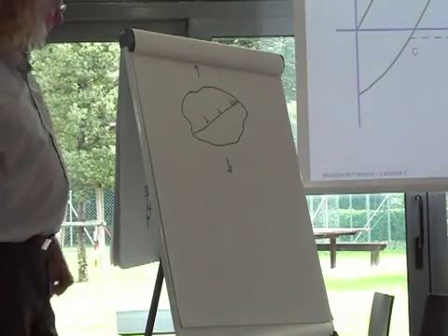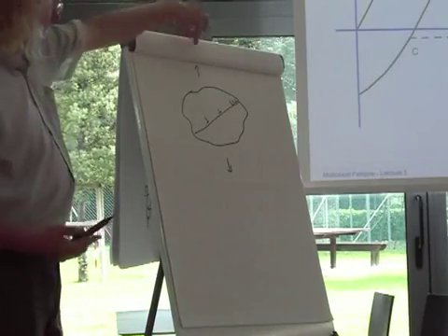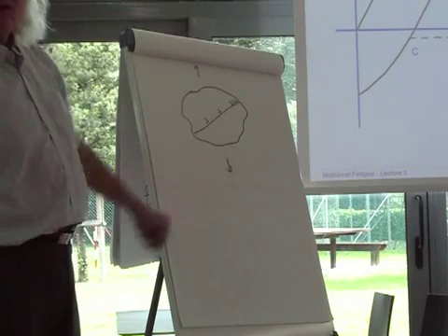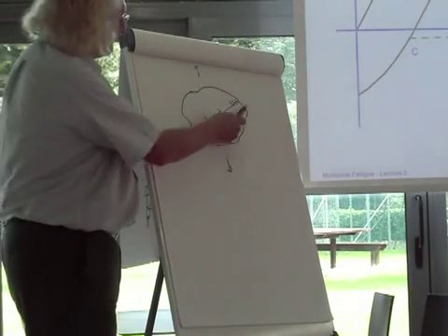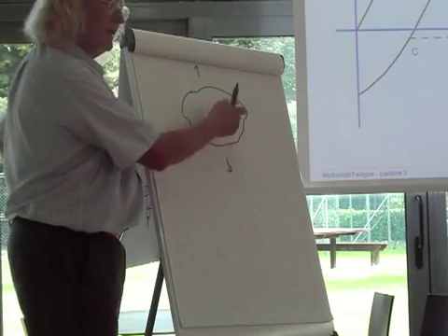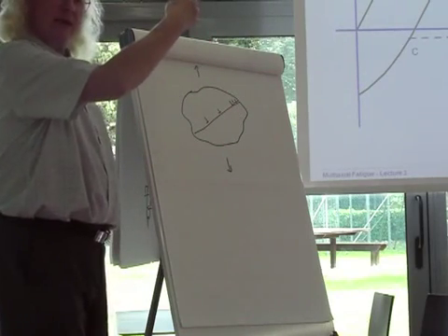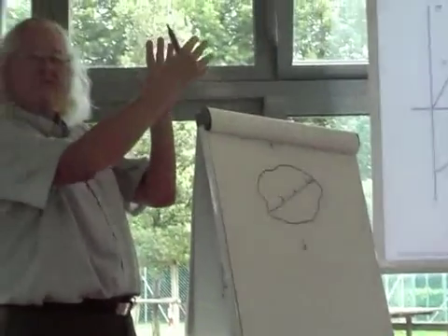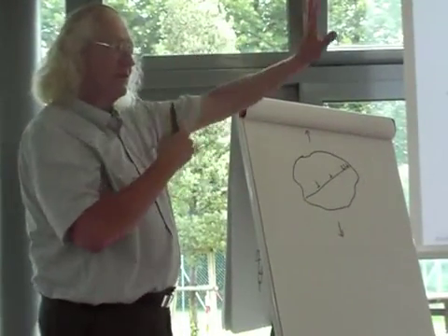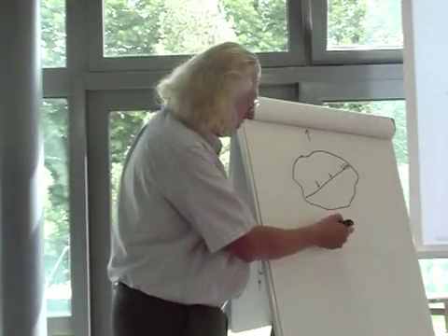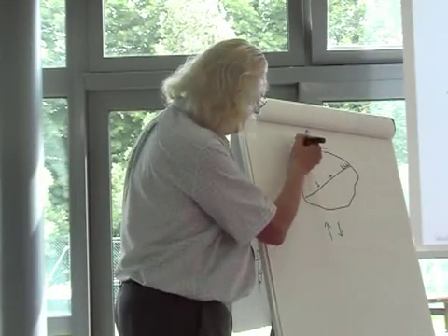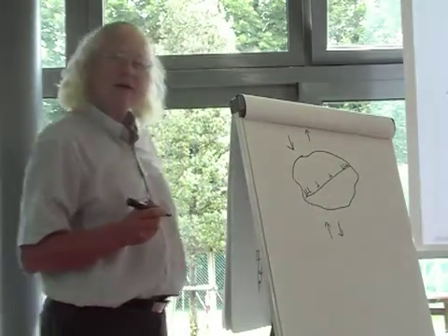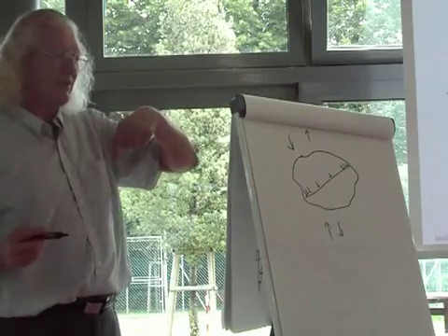But what would happen if instead of pulling this in tension, I push this in compression? Well, if I push this in compression, instead of all the dislocations piling up on this side, and remember these dislocations mean deformation. Remember when I showed you about dislocations moving out of the crystal when they had slip band formation? It's really deforming. Now, if I push this in compression, they'll all pile up over here on the other side, and the deformation will be in the opposite direction.